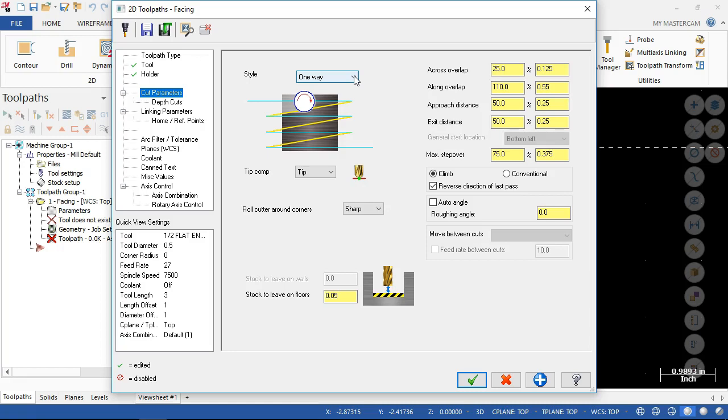And if I really want that fine surface, I'm going to load the table in the same direction, lift up, go back to the start, go one direction, lift up, and go back to the start. If the machine's reasonably tight and not concerned about the backlash, then we can zigzag. One pass would be that we have that 2-inch or 3-inch face mill, and it's just going to find the center line and go all the way across the part.